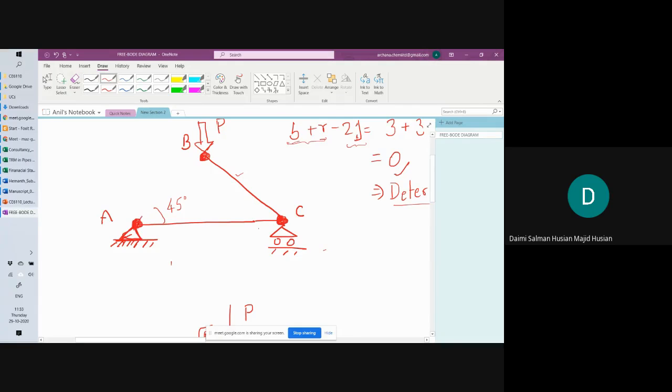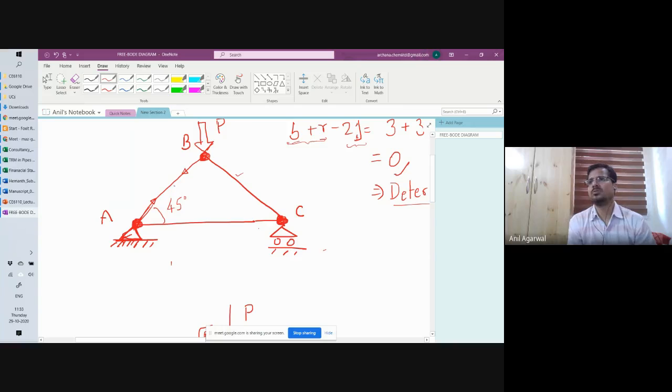But that's what normally we do, sir. Maybe in the books or while doing the calculations. Yeah, different books may follow different conventions. That doesn't matter. How you represent is your call. But if you show forces like this, it is very difficult. Somebody shows forces like these, and I don't know whether I should call it tension or compression, because I don't know whether you are showing this force acting on the member or acting on the joint. Who is applying that force?